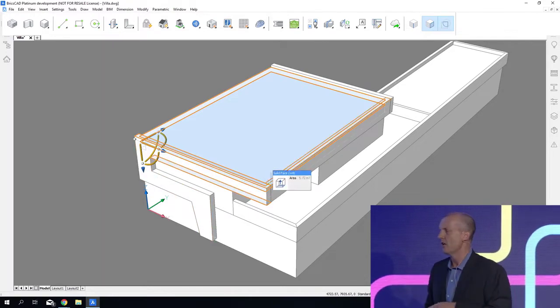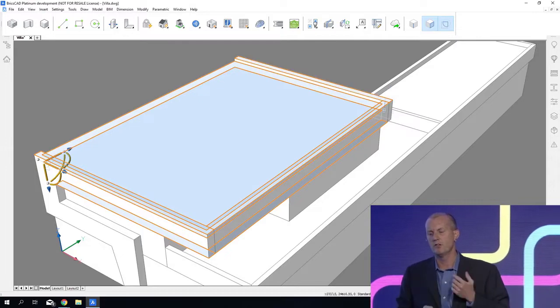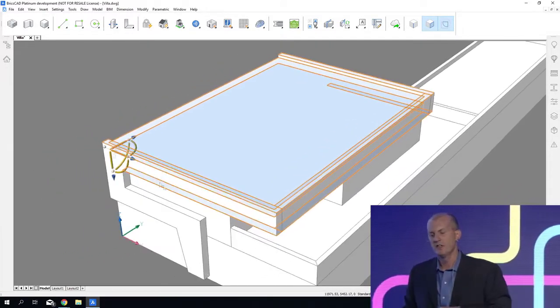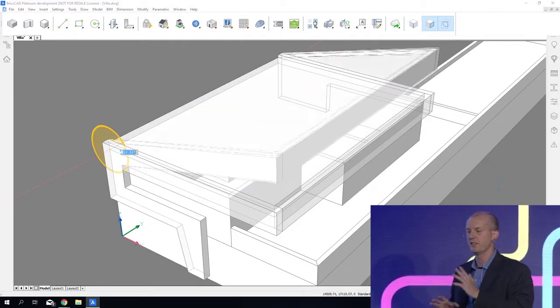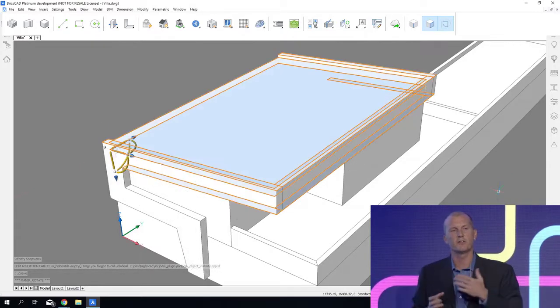If we look at this and say that maybe we want to play with that roof plane a little bit, we can highlight the surfaces of the roof that we want to move. We can also select the bottom and top surfaces of that band. And we can use our friend the manipulator again. One thing to note is that you also have predefined selection options on the manipulator, or you can set the angle that you want directly.